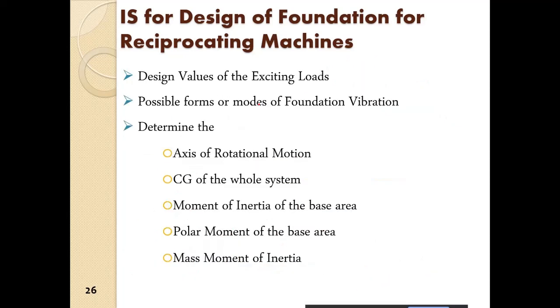So how to design that? What are the steps for designing the machine foundation? First of all, we have already seen the design values of the exciting loads. These will be provided by the machine manufacturer. Then we have to find out the possible modes of vibration of the foundation.